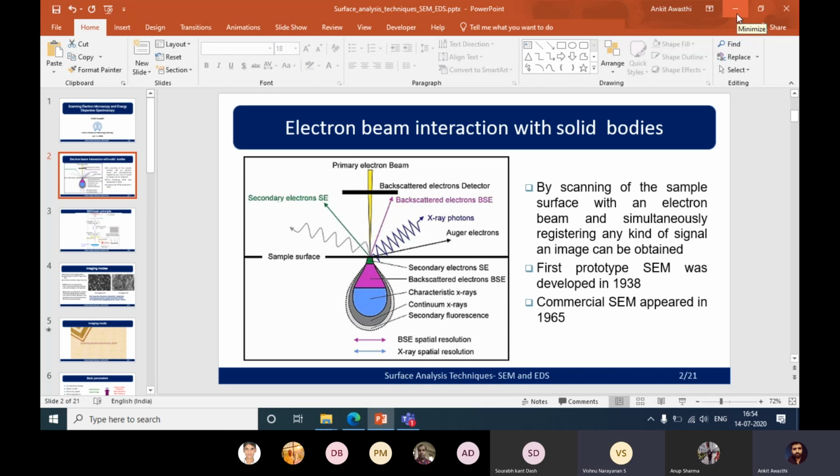Okay, that's what I wanted to know. Actually, if you want to get an idea of the depth, what I recommend is that you cut the sample and then analyze it, and perform a line scan. In that you will get a clear idea up to what depth the composition is varying, because throughout the line we have the same composition, no?